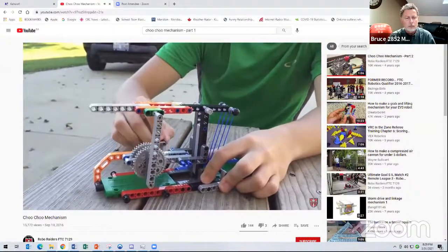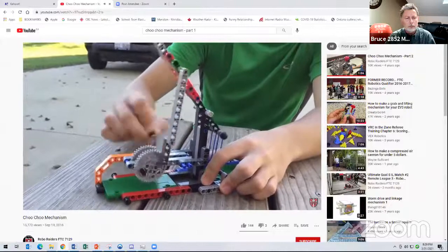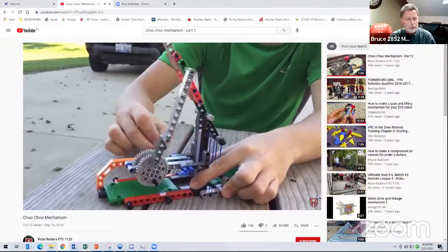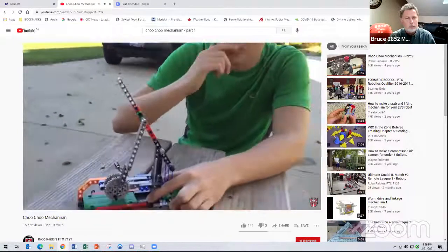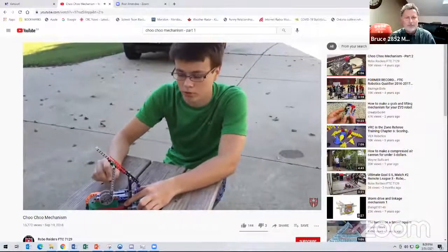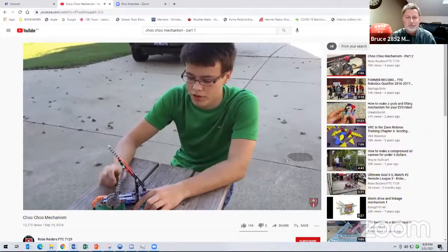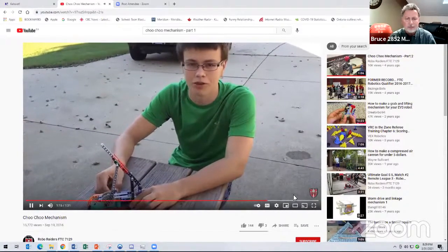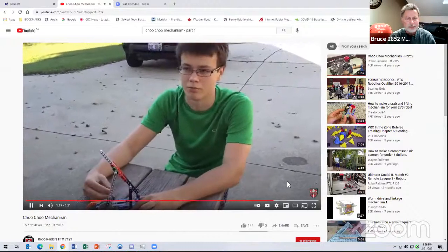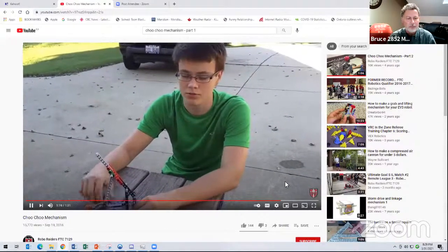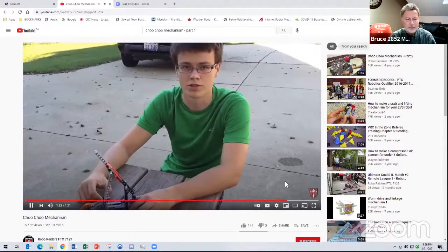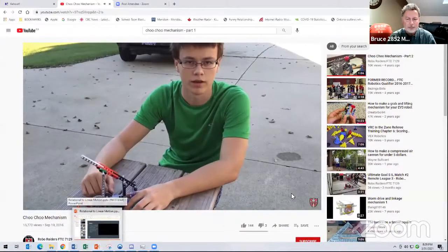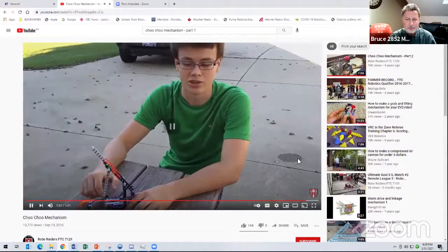And what this system does is allow you to have your motor continually turning. And once the bar gets over center, it will completely release and launch your ball or whatever you've got on your catapult. And that's just what we're using. We're actually just using a single motor on that. So we get our full launch with only one motor compared to some flywheels. So it's a very effective design for this year's challenge, and it actually works very quickly for launching the particles.